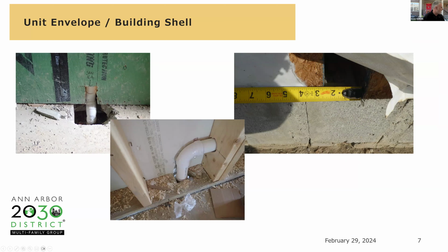Here's plumbing. A lot of times with plumbing, just because it is fitting in a wall cavity, construction isn't perfect. So we're going to get air leakage through this cut in the sheathing. And also, if the foundation isn't sealed up with concrete, we'll get air leakage through there. So here it would be adding concrete into this hole to fill that in.